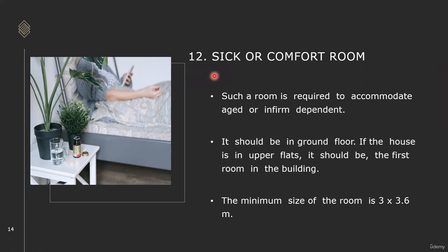In most cases the designer will fail here only. They will do very good plans, everything will be perfect, they will use all the spaces, but the positioning of the rooms is not correct. If you do not position the rooms properly, then the circulation area will be maximized, the circulation area gets more. If the circulation area gets more, then again there is a wastage of area, correct? So always remember the position of the rooms is important.